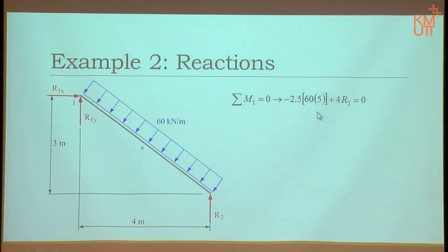Now, how do you calculate moment? It is the force times 90-degree distance. Now, this force here will point down according to these arrows, meaning it makes 90 degrees with this line already. Therefore, there is no need for you to take the x component, y component, because we know that the centroid of this area is in the middle. Meaning in this case for point A, exactly, from here to here is 2.5 and is already 90 degrees. So that's the one.